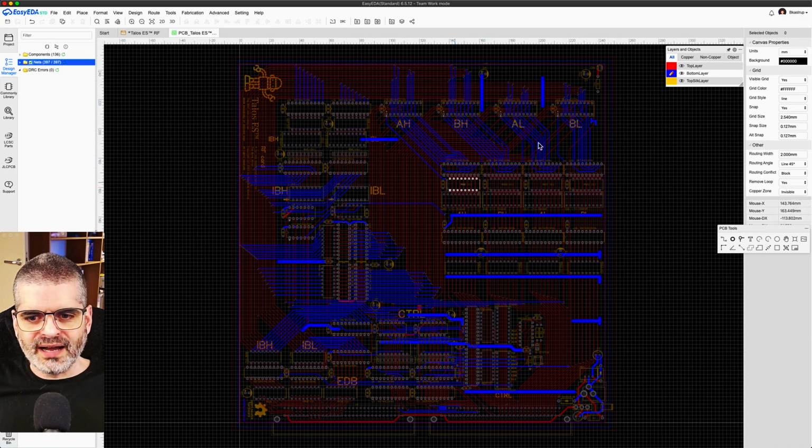But now with CAD tools like this, you don't need to follow that rule blindly, because otherwise you just have a lot more vias than you need, a lot more impedance mismatches than you need. You use the rule only as a rule of thumb, as a best practice. But when you realize that it's definitely better to ignore or even invert the rule, you do it. You just have to know what you're doing. And I chose to do that.